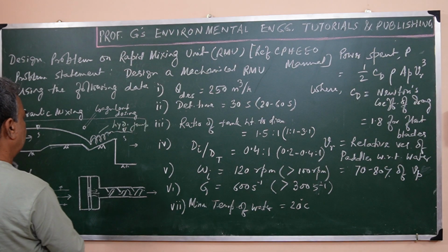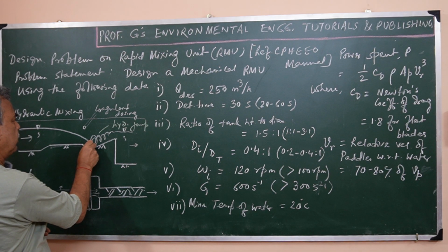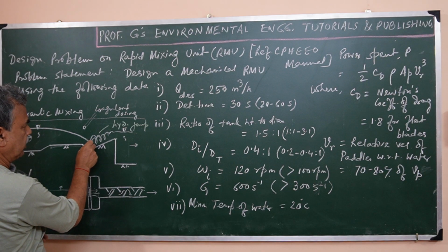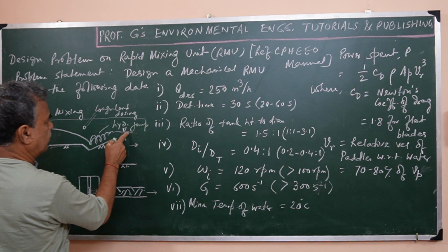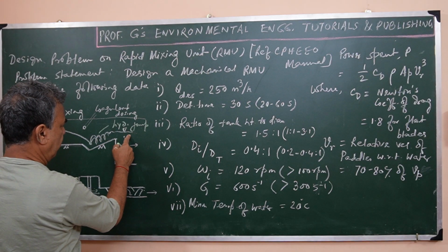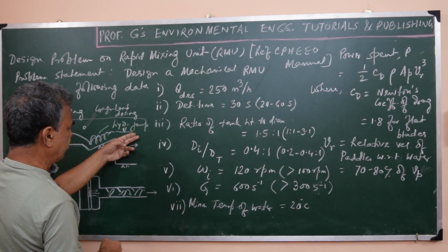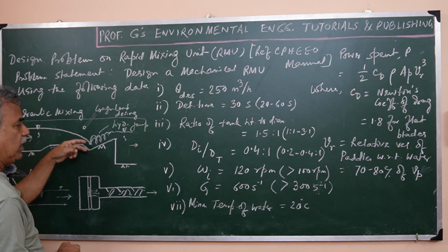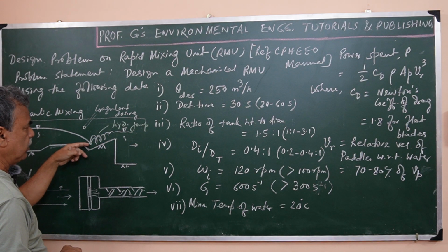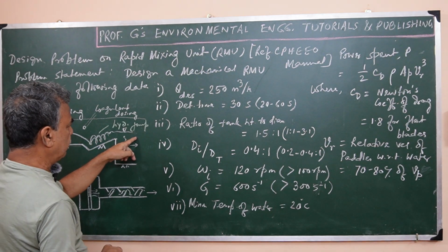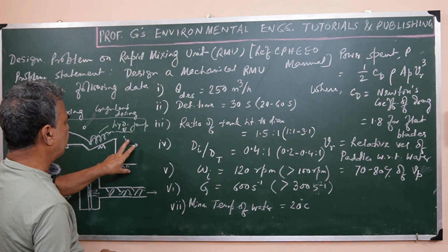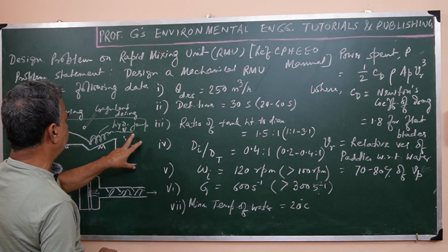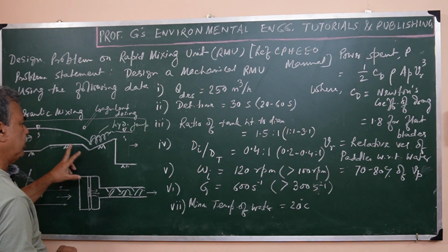So here, as you see in the backwater curves, there is supercritical velocity, and when it meets the subcritical flow, having depth more than critical depth... Here the depth is less than critical depth, so that is why it is supercritical. Beyond the critical depth the depth will be more and the velocity will be less. Here the velocity will be more than critical velocity.